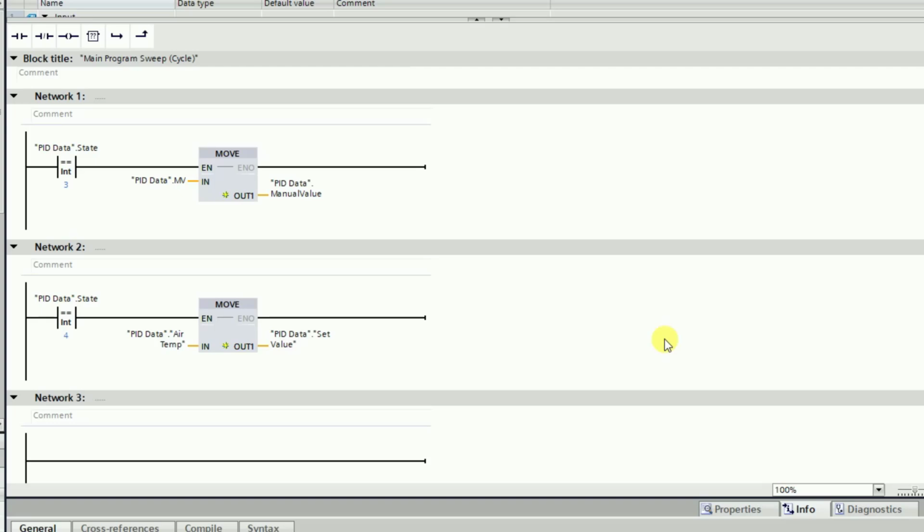During switching of the controller mode from manual to automatic, the controller parameter set value will hold the last process value in controller manual mode. This will keep the set point near the process value during switching to controller automatic mode, which will prevent sudden change in controller output as well as provide a stable and bumpless process operation.